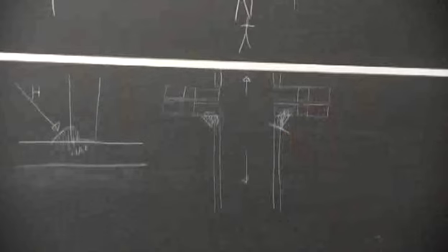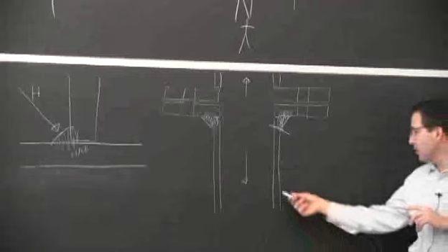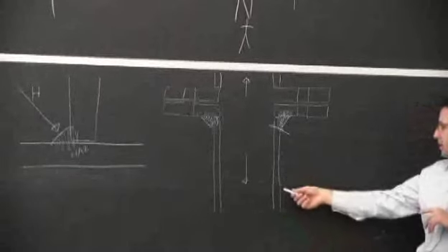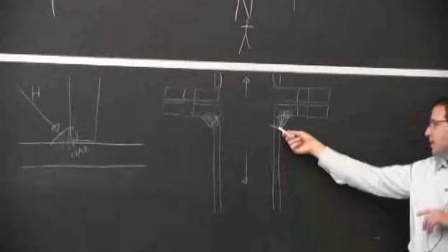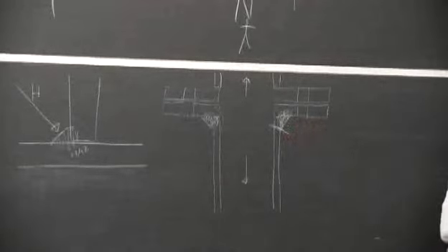The reason I bring that example up is it's the complete opposite to what you'd like to do with welds, because they have a reduced strength. So a lot of times, what's going to govern the thickness of this pipe is or should be how much stress you're going to generate close to the flange.